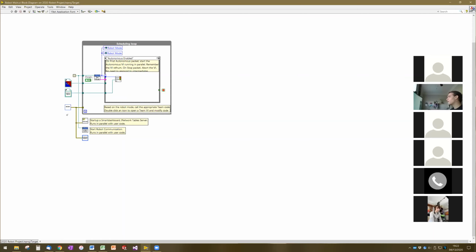There are multiple ways to call a block of code in LabVIEW. The way that we've been working with calling the code in LabVIEW is you take the sub VI, like this one right here, and you place it on the block diagram. And when you loop around, you execute whatever's inside of that block.